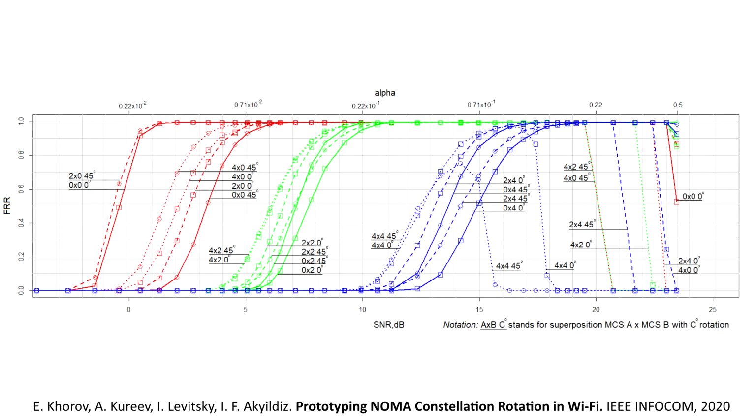During our research, we have conducted a series of experiments to find out the portion of undamaged secondary frames that reach the receiver. We have built a dependency of frame-receive ratio on signal-to-noise ratio for the secondary signal. We vary the SNR by changing the alpha parameter, which is the power fraction of the secondary signal.